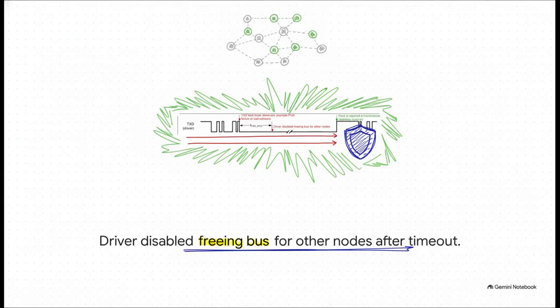Once that specific timeout window expires, the TCAN1042 just cuts off the babbling driver. Instantly, normal communication from all the other nodes on the network is fully restored. The bus is totally free again. It essentially stops a localized failure from snowballing into a system-wide blackout.